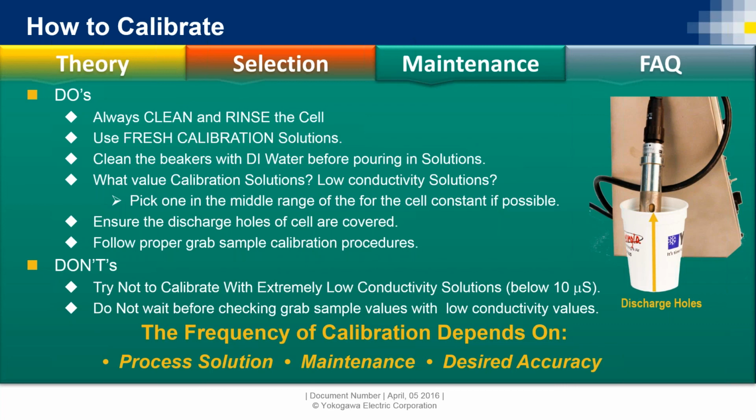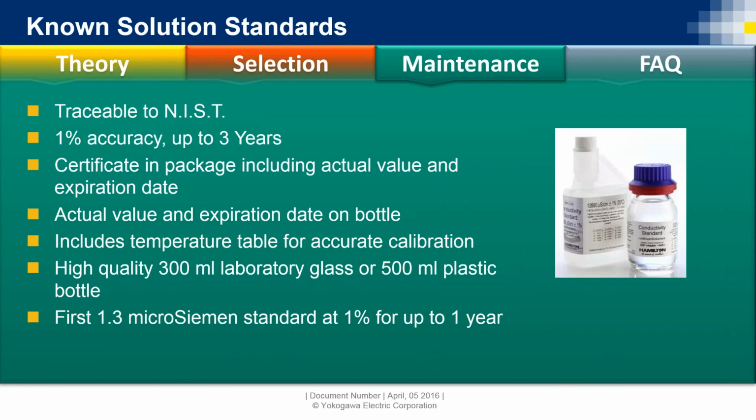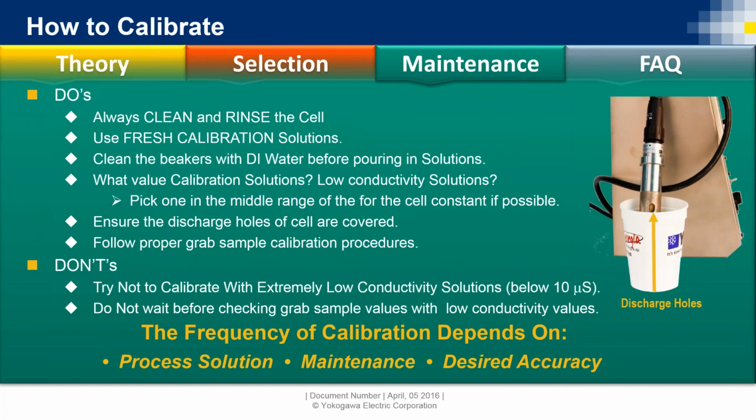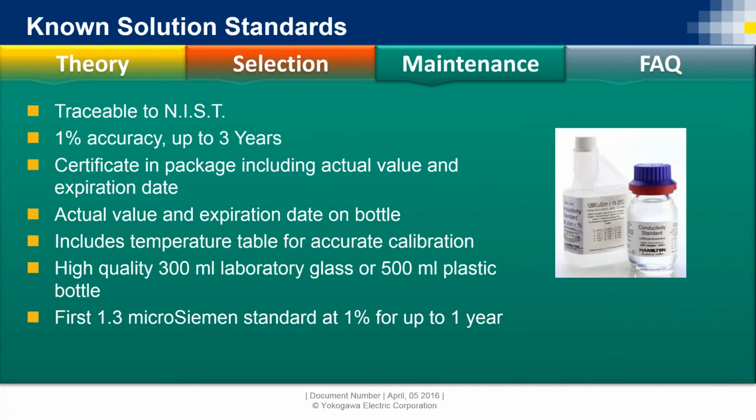That way, if there was any soap or something else that would have a conductive charge to it, conductive ions dissolved in solution, it doesn't interfere and contaminate your buffer solution. And then what we'd say don't do is, if possible, we want you to do air calibrations below 10 if you're in ultra pure water, and we'll show you why in just a moment.